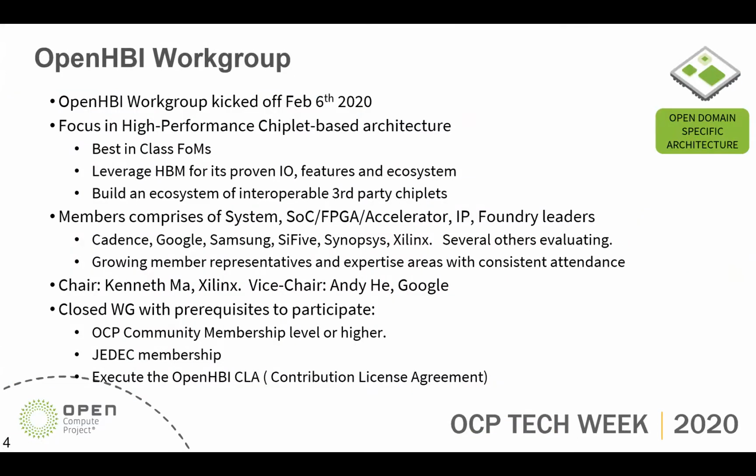So OpenHBI stands for Open High Bandwidth Interface. The workgroup kicked off earlier this year, on February 6, 2020. The goal is to drive OpenHBI as an open, public, royalty-free, high-performance chip-to-chip interface standard. The primary focus is to achieve best-in-class figures of merit, including bandwidth per millimeter, energy per bit, and latency. Most of us would agree that chiplet-based architecture will be one of the main pillars in the post-Moore's Law era.